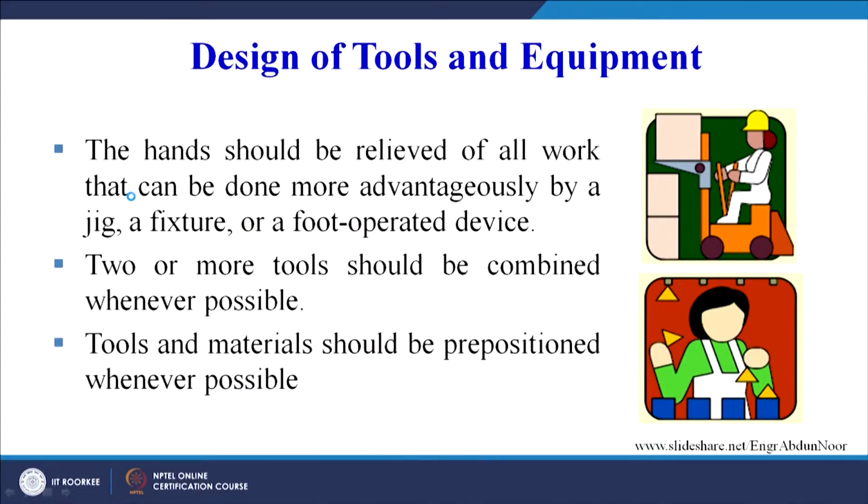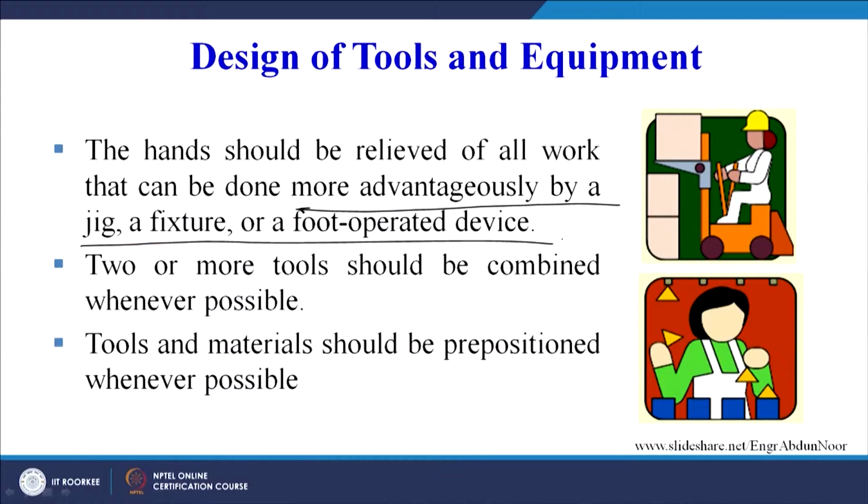The hands should be relieved of all work that can be done more advantageously by a jig, a fixture or a foot operated device. So wherever possible we can distribute the work among our different limbs. I have already given an example that when we drive a motorbike we can control with both hands and with both feet. So wherever possible we can use our feet to control the machines or equipment.